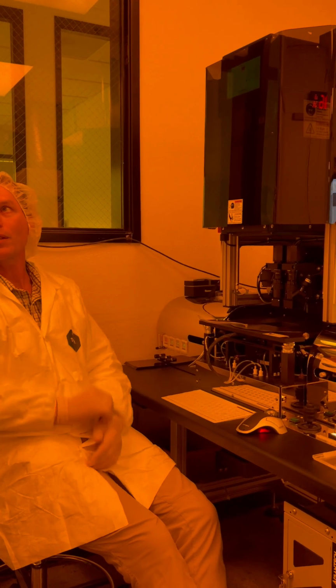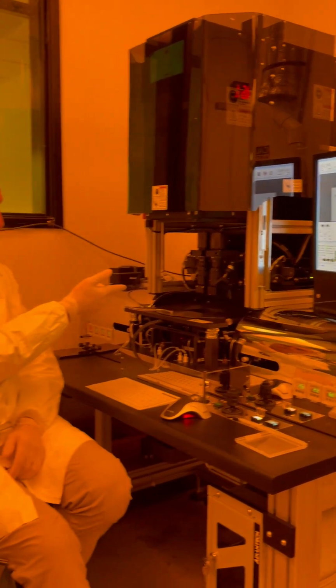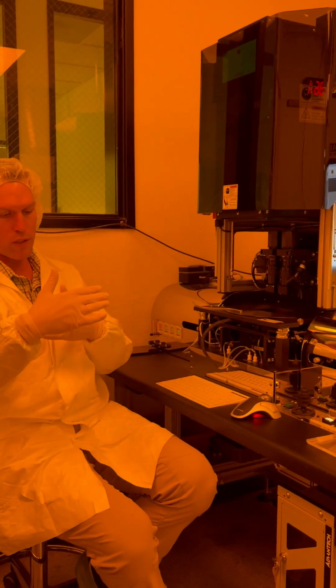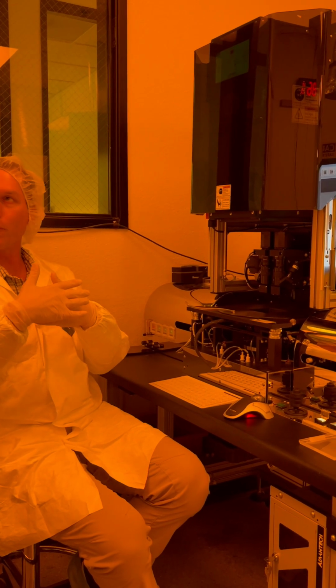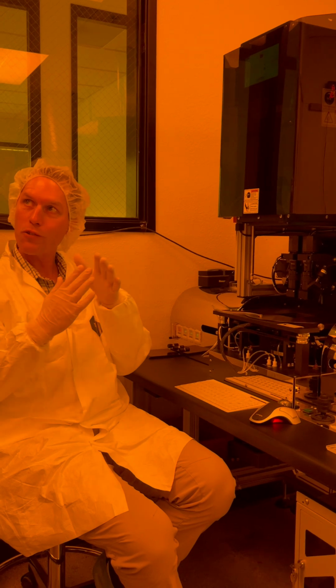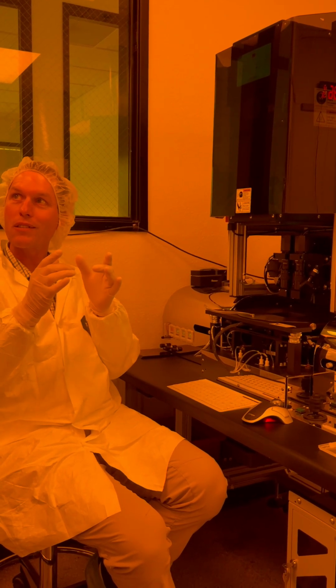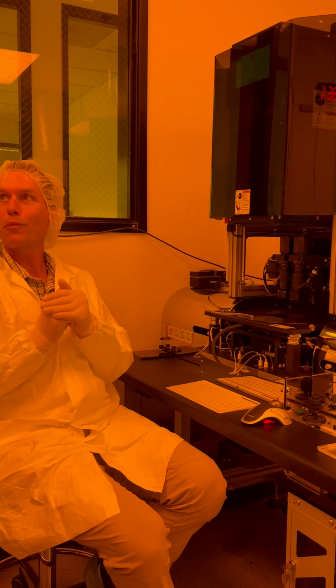Okay, interesting. Okay, cool. And the way we sense the height is once those three spacers touch, there's a downward force on the chuck. And we're measuring the pressure of that nitrogen that's flowing. So that pressure will increase, and we say, okay, now we're there.